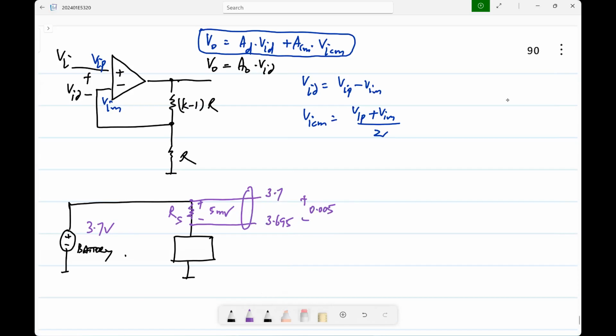Now, of course, the next thing is you can ask why not put the resistor here where the common mode is small, but typically that is the common ground where lots of things come together. It's usually a lot more difficult to lift that up than do it from the supply line. In fact, this part could be part of the battery itself. The battery has some small resistor built in and it has some outputs to give you the state of the charge. There are many cases where you have to measure a small difference around a large average value. That is inherently difficult.